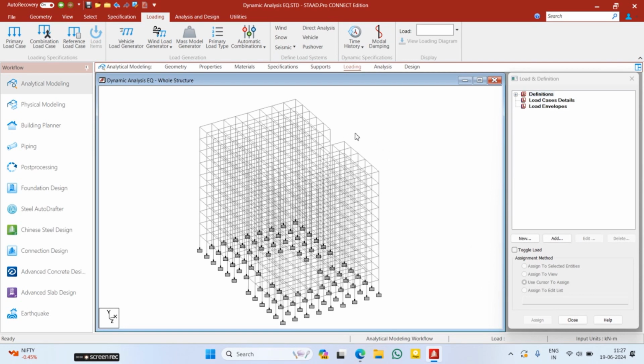For that, let's say I'm taking my building in Delhi. Whichever the height is, it's not an issue for dynamic analysis, because if your building is in zone 3, 4 or 5, there is no height criterion for dynamic versus static analysis. You have to do the dynamic analysis for whatever the height in zone 3, 4, 5.